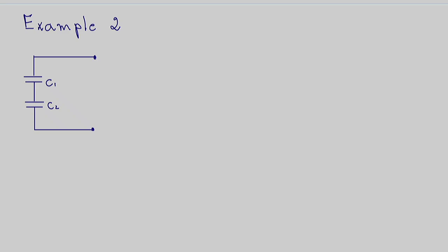What are the options we have? I want to simplify, I want an equivalent circuit, therefore I have two choices: apply dV test dt or I test. What would you apply in this case? I test, because when elements are connected that way in series, the current will be the same. Very good. So let's do it. You can go ahead.